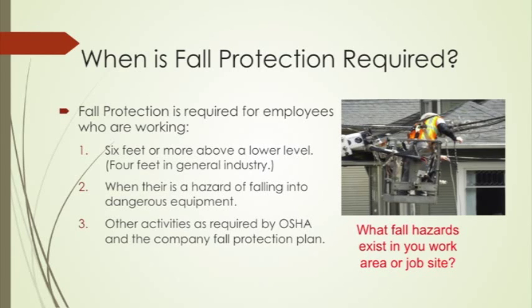When working around dangerous equipment that an employee can fall into, fall protection should be provided even if the height is lower than 6 feet. If your employee is unable to identify the hazards, it is important that your competent person point them out and ensure that your employee is properly protected.